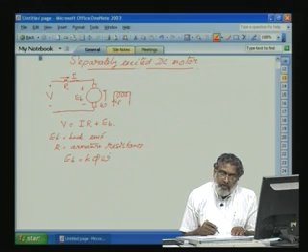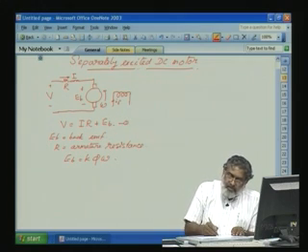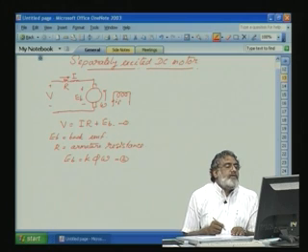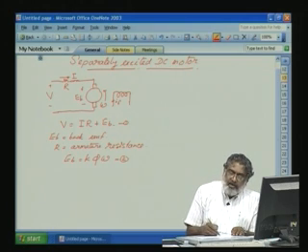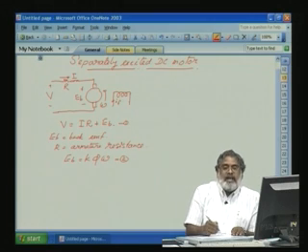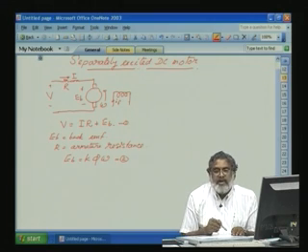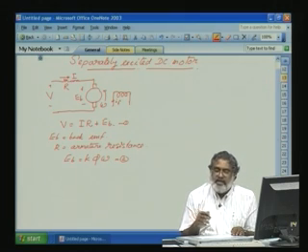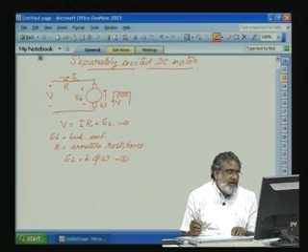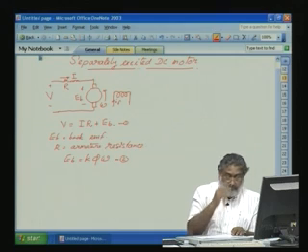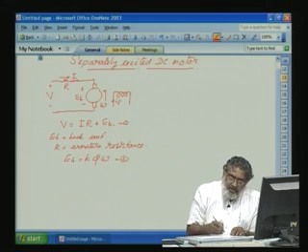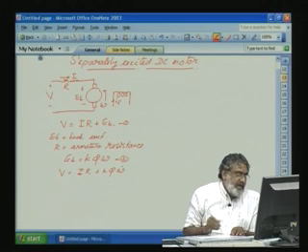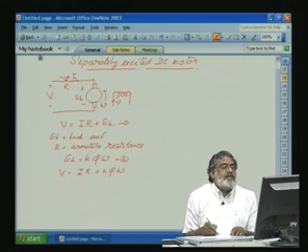Now we will substitute equation 2 into 1, introducing omega into this equation. Later we have to introduce the torque, and from this we get the relation between torque and speed. Then we will find the torque speed characteristics of the machine for variable conditions. So EB is equal to K phi into omega. When you substitute, V is equal to IR plus K phi into omega. This K phi is a constant for a machine.